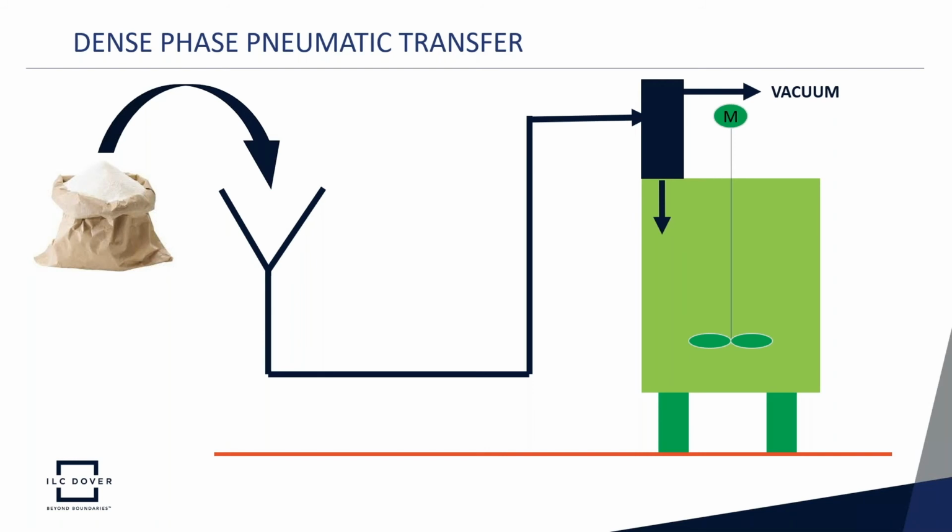The discussion of pneumatic powder transfer using dense or dilute phase is a webinar series in itself, but let me just summarize here that dense phase transfer has a proven capability to move a vast range of powder types, and is thus more suitable to this application, where one tank will be charged with dozens of different powders with great variance in their physical properties.